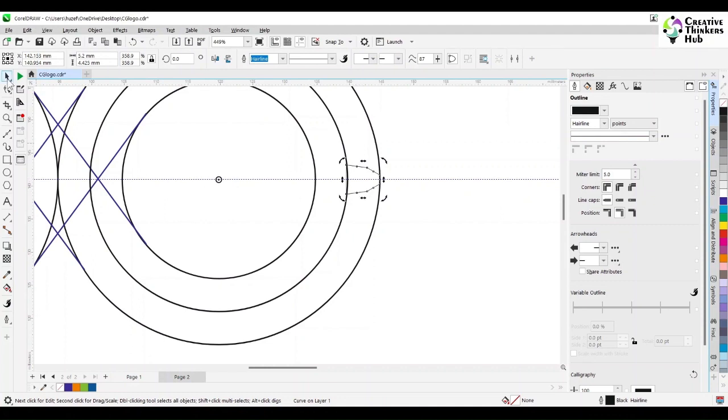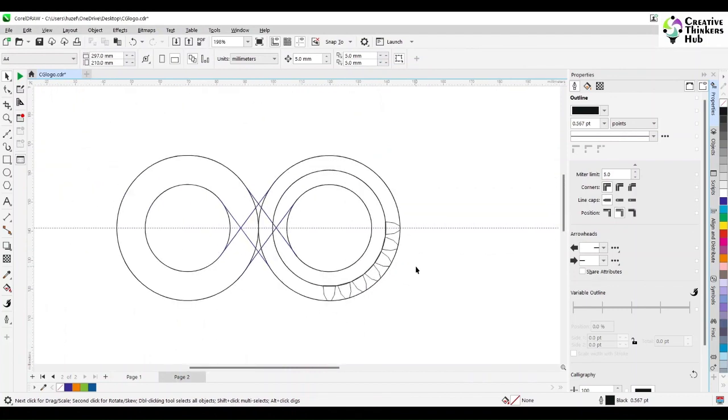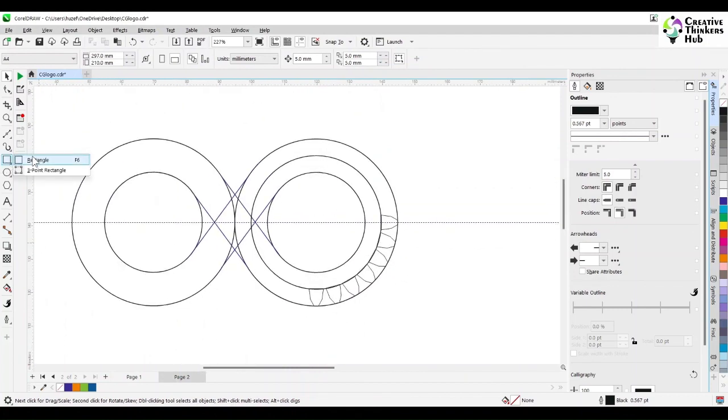So you copy paste this, rotate it, keep the pivot point, press control and left click right click, and then just duplicate to complete the remaining, and delete that extra gear that you have created.